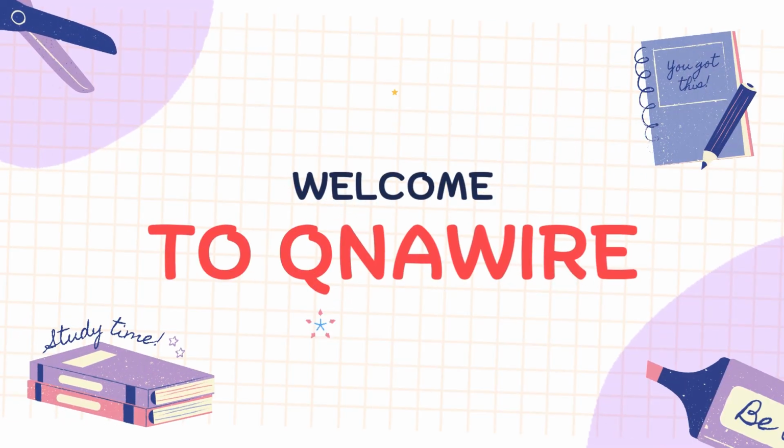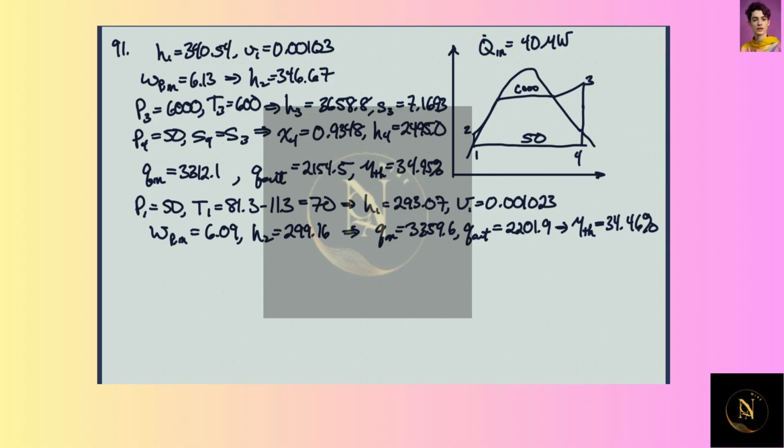Welcome to qnawire. In this problem, we have another simple Rankine cycle with steam. This time we have a saturated or a two-phase fluid coming out of the turbine. Again, the low pressure is down here at 50 kilopascals. High pressure is at 6 megapascals.